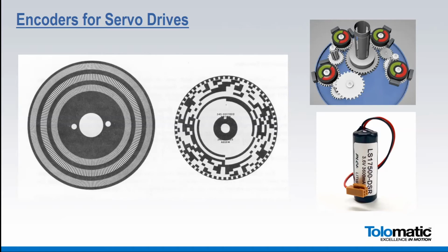Over on the right are two other ways that manufacturers have evolved to create absolute encoders. The one on the top is a geared absolute encoder. So they do what that expensive disk in the middle does, just through a bunch of gears, and you can know where your encoder is within one revolution. And many times these encoders will allow you to have absolute position within a high number of revolutions, say 4,000 or 16,000. Then the other way to do this is using battery-backed encoders.